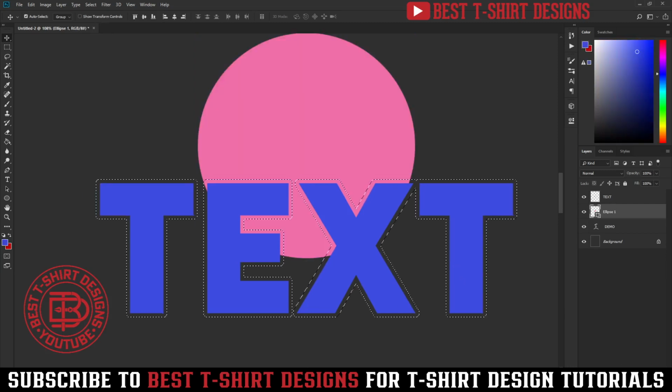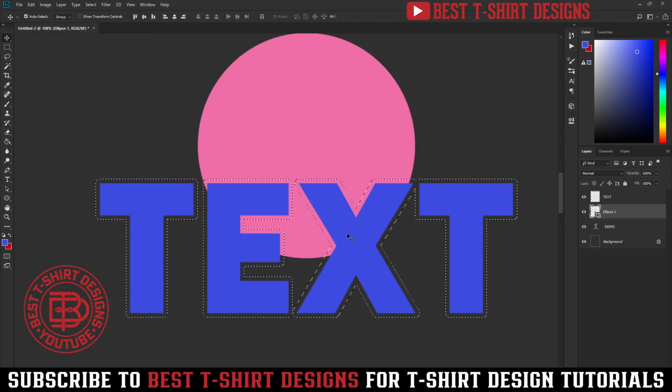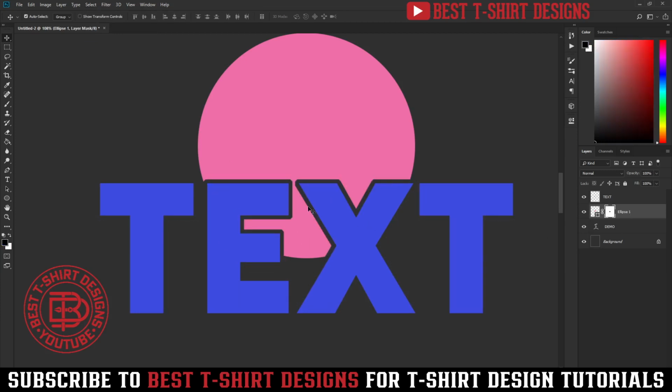Not like that. Once it is selected like this, you have to press Ctrl Shift I, or you can simply go to Select and then Inverse. Inverse will make the selection in the opposite direction, and once you do that, now you can select this ellipse and click here. It is going to give us that cutout effect or offset path effect.